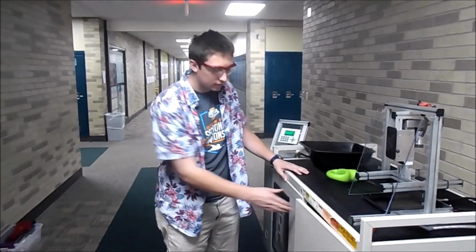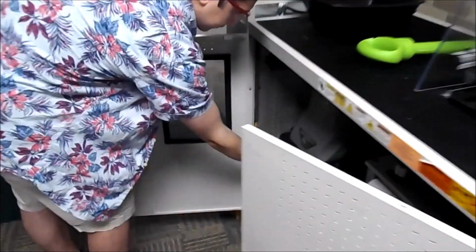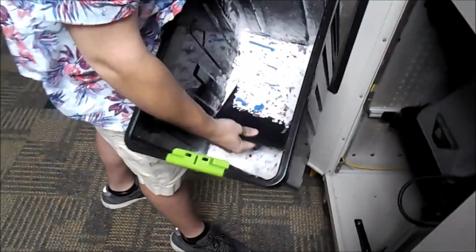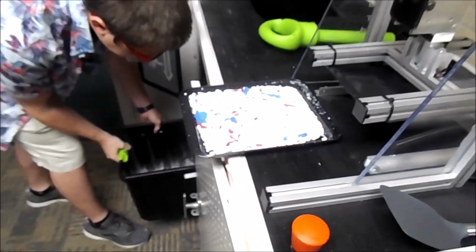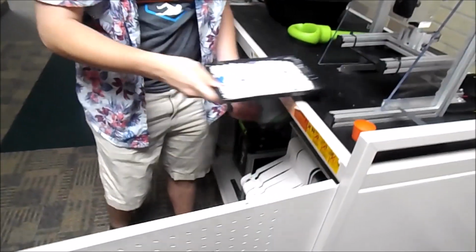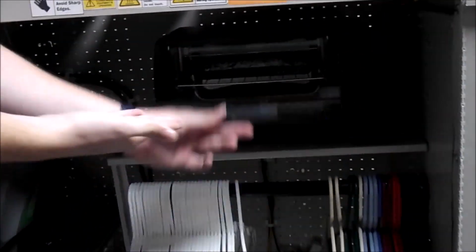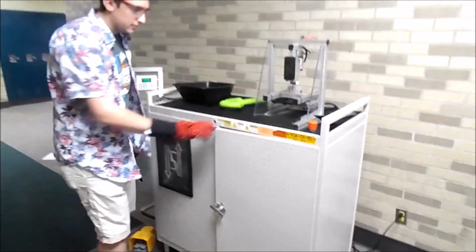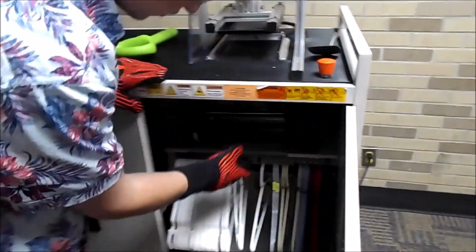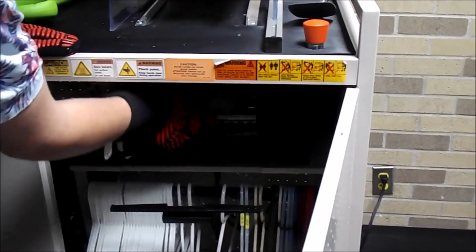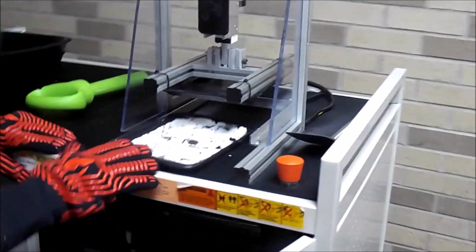One starts the shredder. After we finish shredding, the hangers come out like this, in small pieces. After which we scoop a few into a pan. We don't have a specified amount quite yet, but we will soon. And we place said pan in our oven. After about 15 minutes at 350 degrees, the plastic will have melted, and making sure you have heat-resistant gloves on, you take it out and put it underneath the press to flatten it.